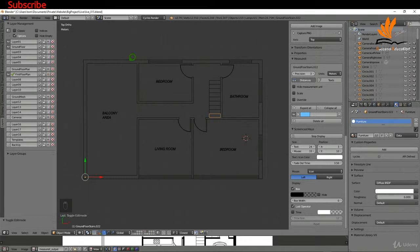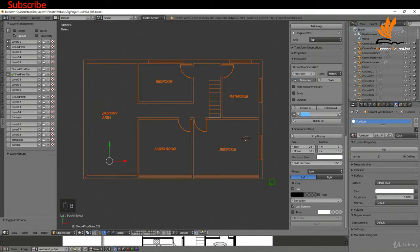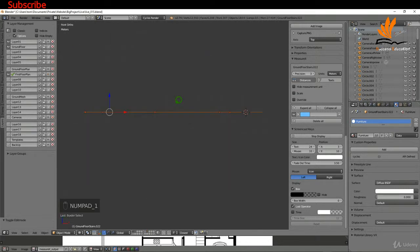The other thing I want to do is move this first floor into its position on the Z axis in relation to the ground floor. So I'm going to press B for box selection. Select all of this, press 1. I'm going to press G, Z to restrict it to the Z axis, and it's going in the positive direction. So I'm just going to type in 2.7, which is 2.7 meters, and press enter.